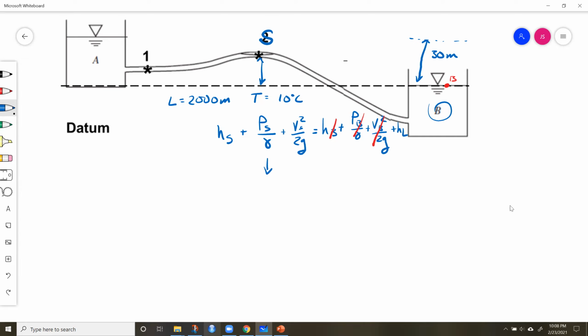Moving on, we can set our pressure head term here to that standard rule of thumb value. We said that was about 2/3 of the atmospheric pressure, which was -10. So that gives us -7 meters. This is just an assumption, a design standard here, that we don't want our pressure head to go below -7. If it goes below, it's getting close to cavitation.